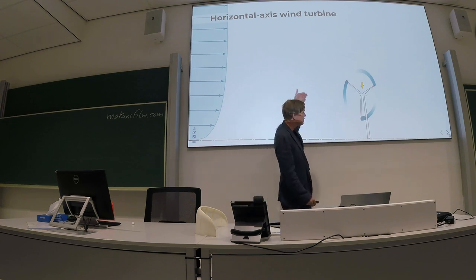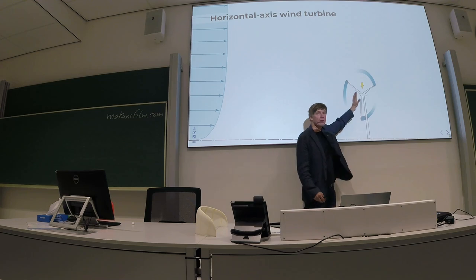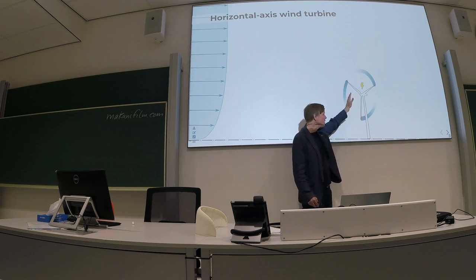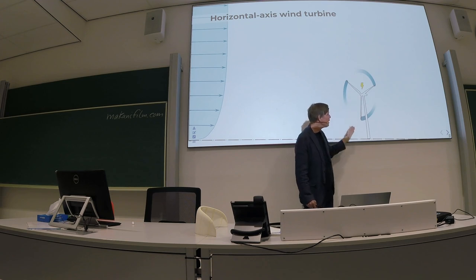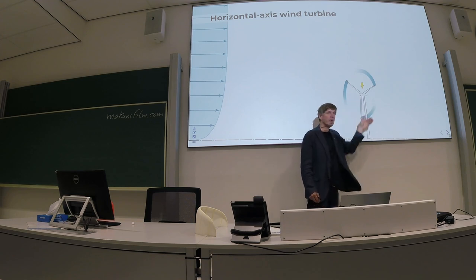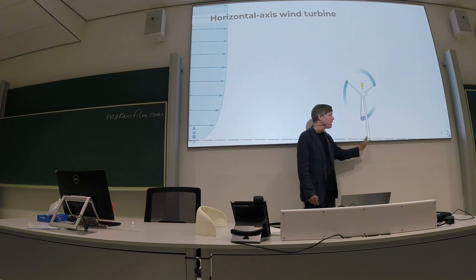Because when the wind comes, there will be a thrust acting on the turbine nacelle, and this thrust will create an overturning moment, and the foundation needs to withstand that.